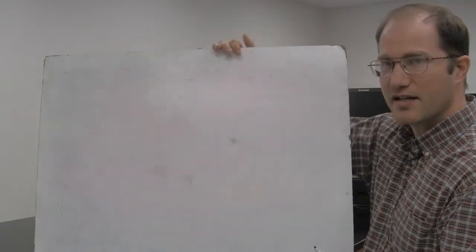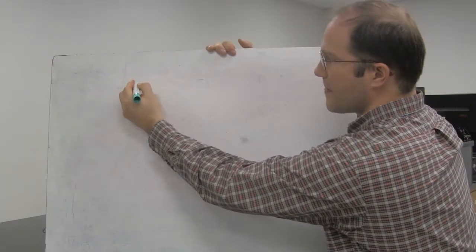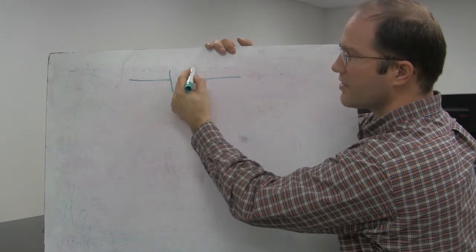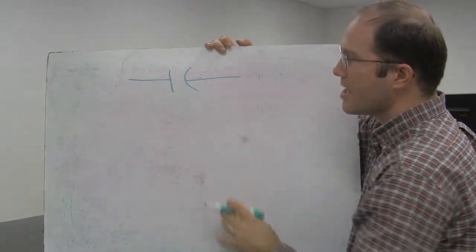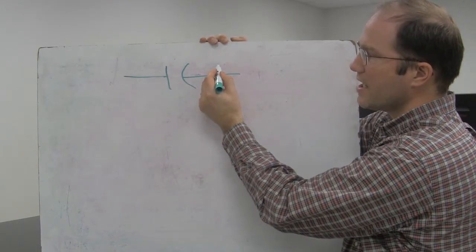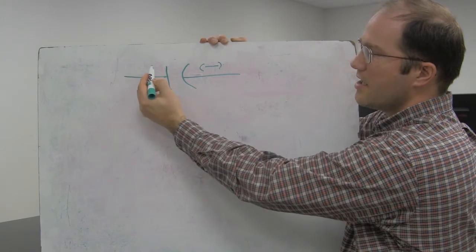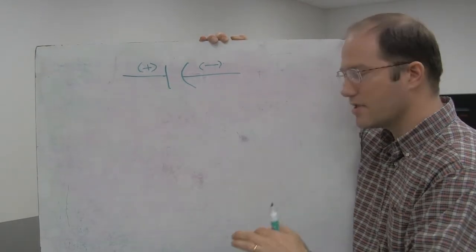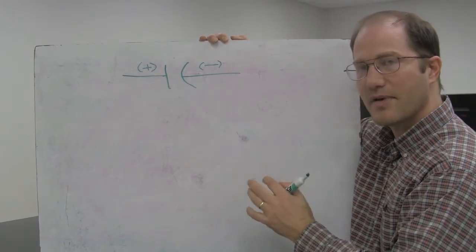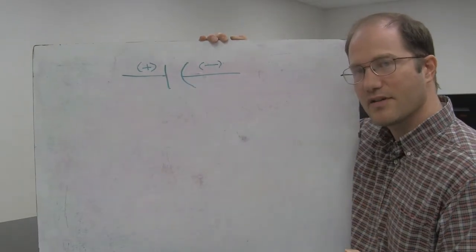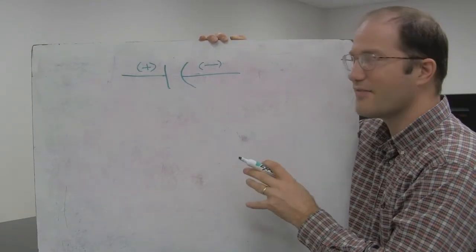First of all, whenever you have a capacitor, let me draw a schematic diagram of what the capacitor looks like. You have a wire, a straight down line, and then a curved line like this. The curved line is my negative side, and the straight line is my positive side. When you're using electrolytic capacitors that tell you which side is negative and which is positive, it's very important to make note of that convention.